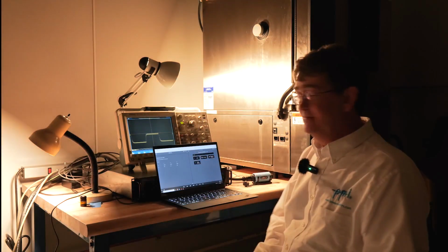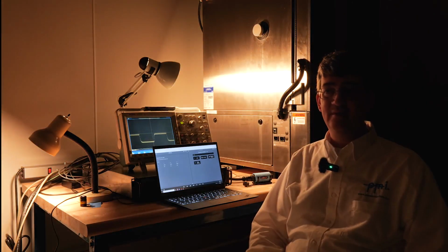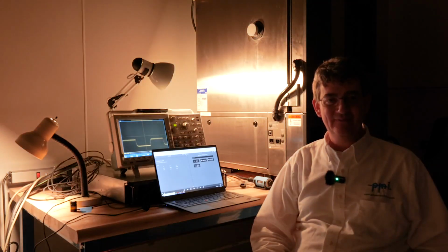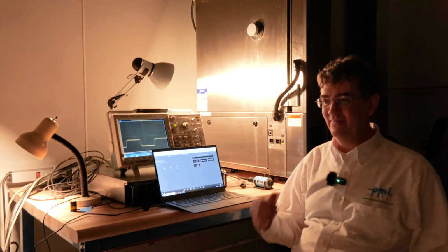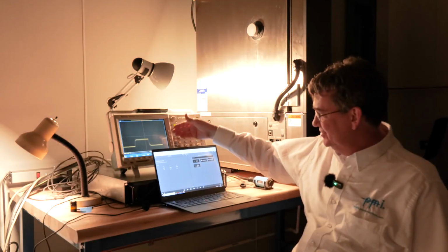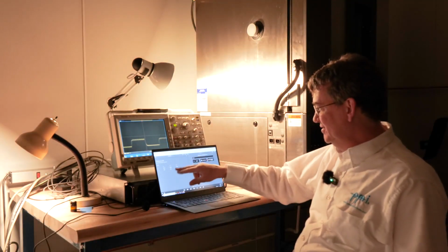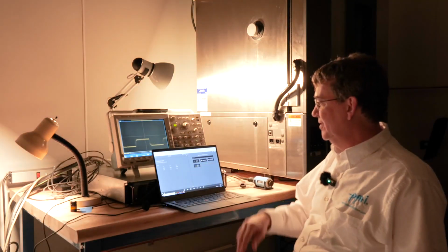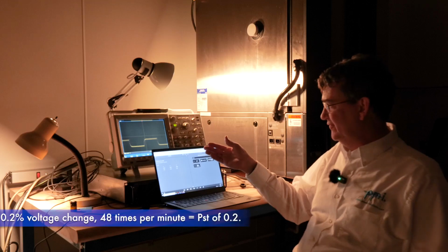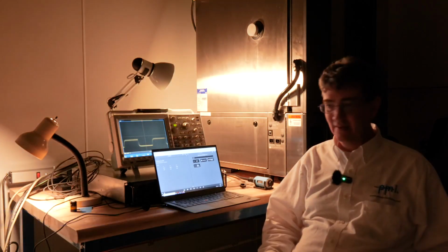And we will let the Bolt process this data and make sure that it's going to be measuring well on the high end. Right now we are checking the Bolt's very high flicker level measurement. We have a 20% voltage change. We can see a very large change in light output from the sensor because this is a huge amount of flicker. We check here in PQ Canvas. We're measuring 21, which is the right amount for this level of flicker. That's the top end of the recommendation for the dynamic range of a flicker meter.